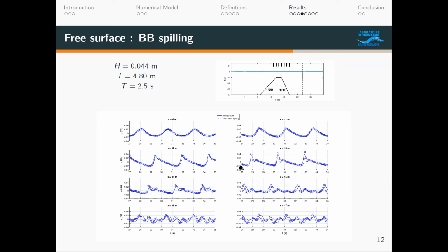And overall, there's a good agreement. And so wave breaking is seen at about 12 to 14 meters. Observing these free surface elevations after these gauges helps us in determining what kind of termination criterion we want to look at. And like I said earlier, we selected u equal to 0.3 to terminate iteratively by looking at values at these gauges from this test case and the other test cases that follow.